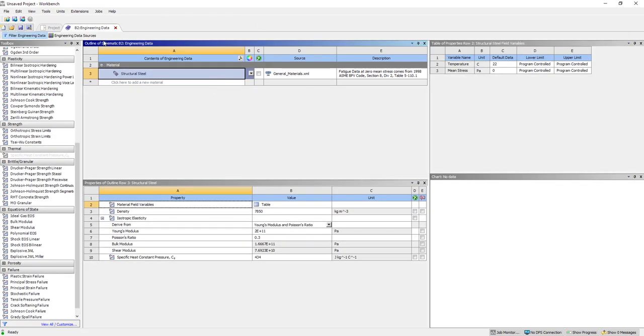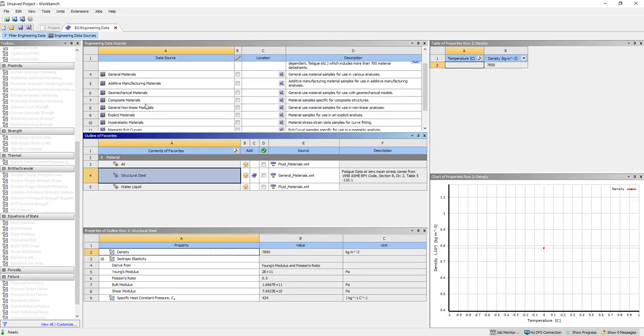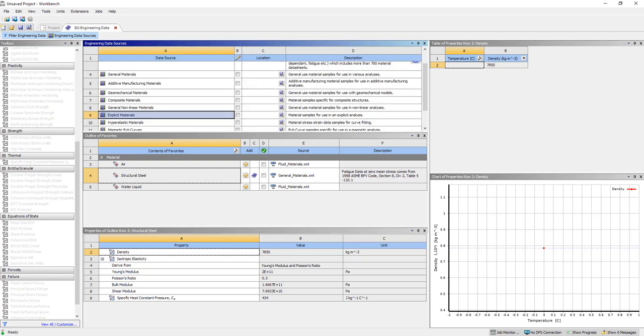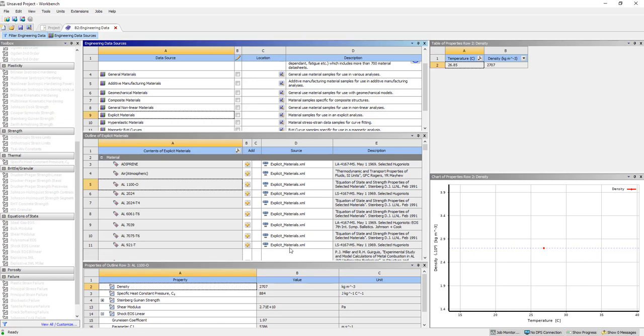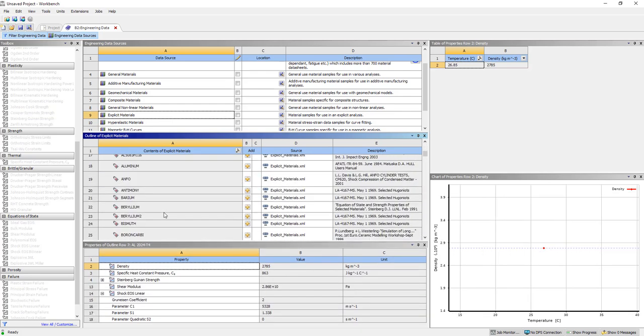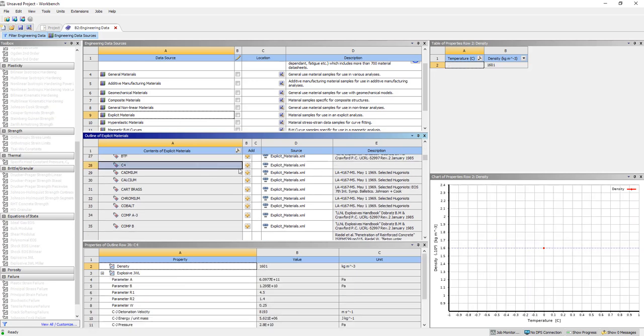This is the Ansys Engineering Data Material Setup tool. We want to go to the Autodyn or Explicit Dynamics materials because this is where all of our explosive models are stored. Okay, so these are all the Autodyn materials. You can see we have various types of aluminum. And if we're looking for explosives here, we can, for example, find our C4 explosive material.